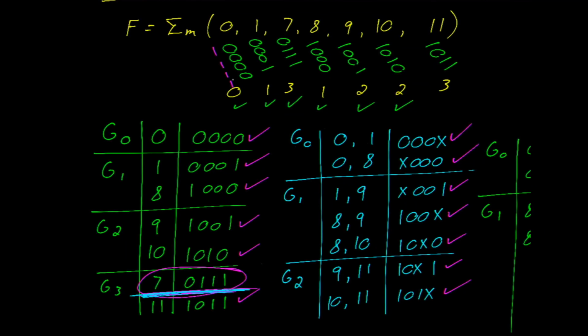For systems with 5 inputs, the K-maps become 3-dimensional. With 6, 7, or 8 inputs, the K-maps become completely useless. However, the Quine-McCluskey method still works. It's tedious, but it works. It would work even better if you wrote a computer program to automate the process.